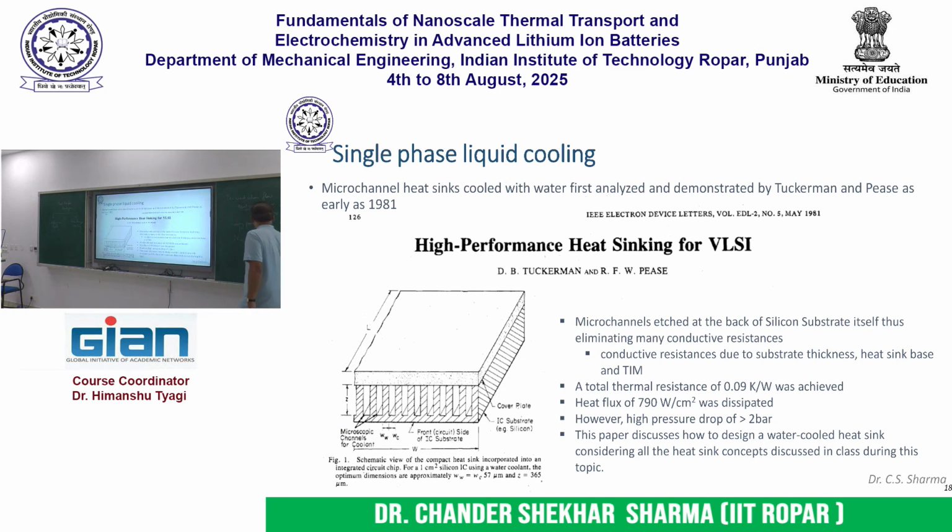So the Nusselt number, h d by k, is a constant, right. Here h is your heat transfer coefficient, d is your hydraulic diameter, and k is the thermal conductivity of the fluid, right. So this means that my heat transfer coefficient is inversely proportional to the hydraulic diameter. So if I reduce the hydraulic diameter, I can increase the heat transfer coefficient, right. This we know from undergraduate heat transfer, right.